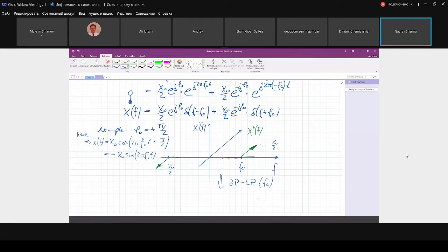This is just the Fourier transform, and usually the Fourier transform is complex. I just show in this diagram, on this axis, the imaginary part of the spectrum, and this is the real part. Since we only have an imaginary part for this signal, there's an odd symmetry.